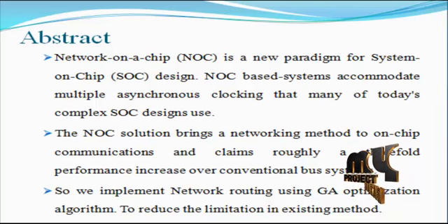Generally, integrating the network on chip into the SoC provides an effective means to interconnect several processing elements or intellectual properties, such as processors, memory controllers, etc. The NoC medium features high modularity, flexibility, and throughput. The NoC comprises routers of interconnect, allowing communication between the processing elements and other intellectual properties. The NoC relies on data packet exchange along the path of routers defined by the routing algorithm.